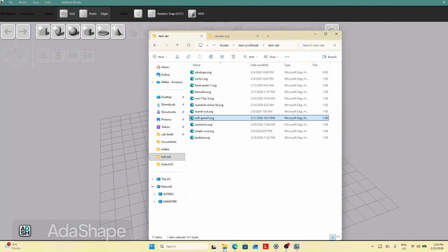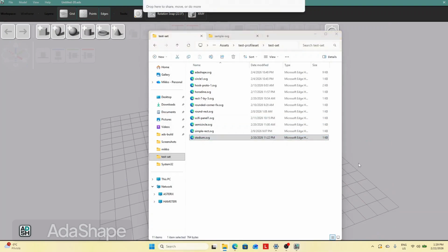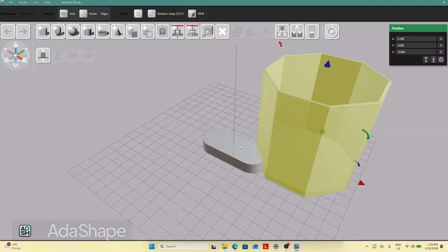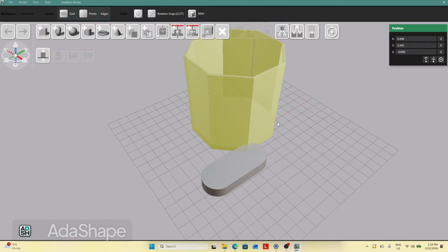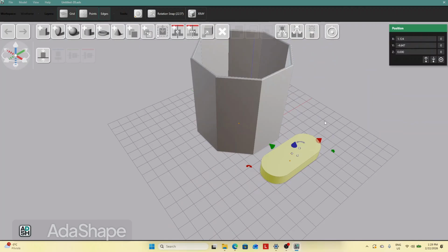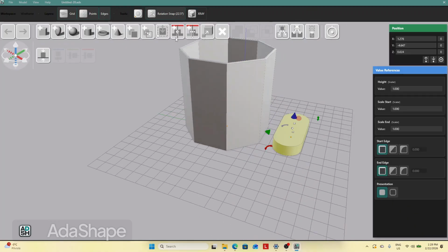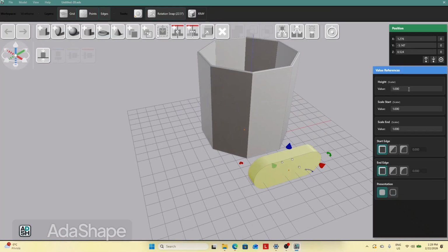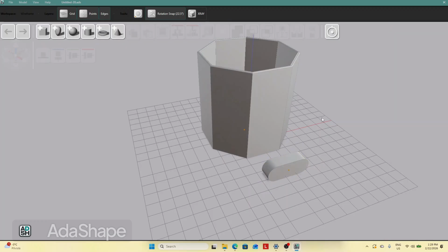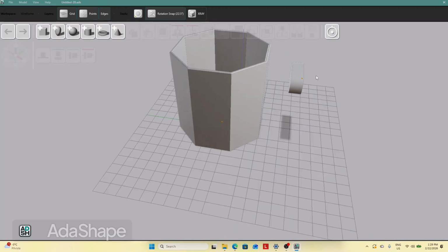And usually desk organizers like this have these holes as details. So let's add a nice hole here. Oh, sorry. Let's add, so now what I'm doing, I'm putting the rotation snap on, so we can have these nicely planned rotations. And let's put the scale to 0.6. That sounds good. Then we can just drag this guy over here.